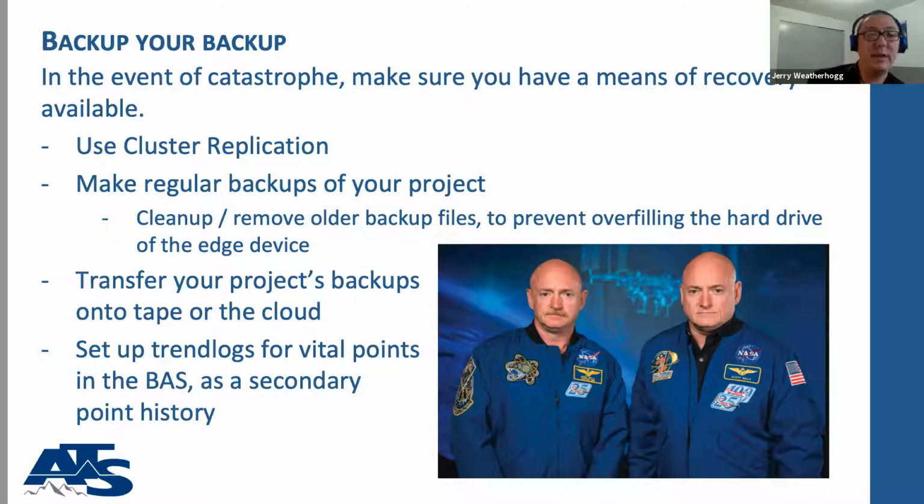And lastly, it's a good practice to set up trend logs for vital points in your control system as a secondary means of point history. So if there's any issues with your edge analytics device polling a certain controller for its point data, you have a second source of that point data that you could query and retrieve.